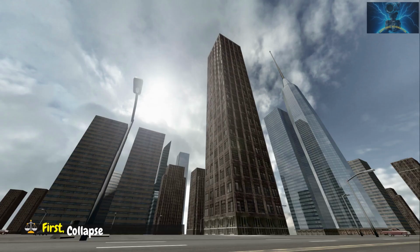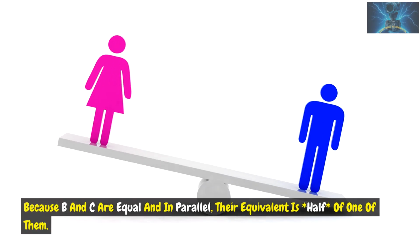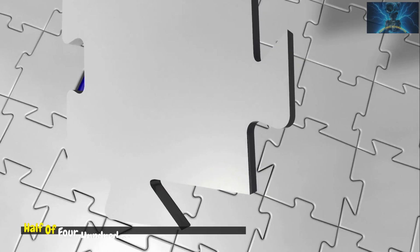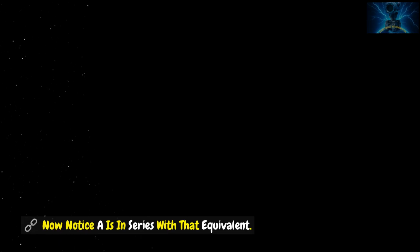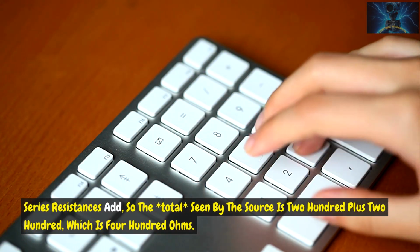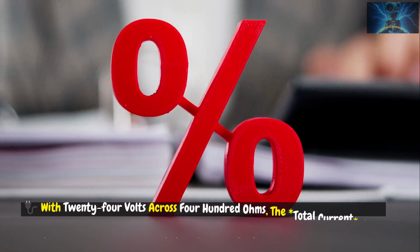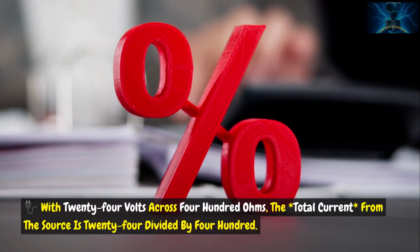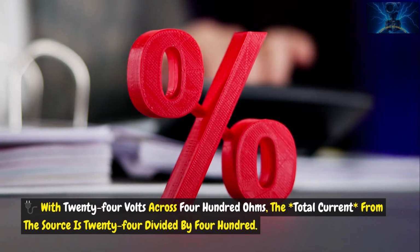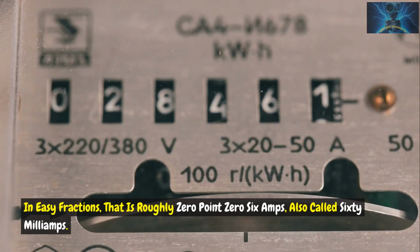Reduce to an equivalent. First, collapse the parallel pair. Because B and C are equal and in parallel, their equivalent is half of one of them. Half of 400 ohms is 200 ohms. Now notice A is in series with that equivalent. Series resistances add, so the total seen by the source is 200 plus 200, which is 400 ohms. Solve the total. With 24 volts across 400 ohms, the total current from the source is 24 divided by 400. In easy fractions, that is roughly 0.06 amps, also called 60 milliamps.